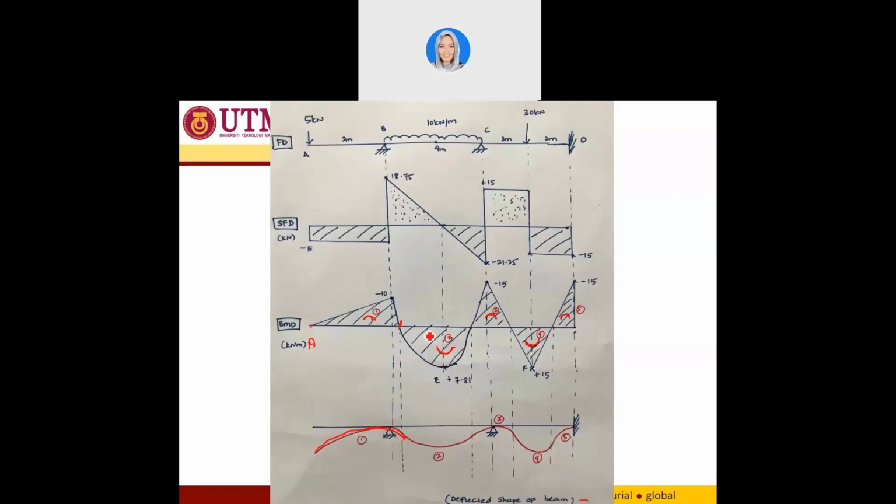Now between this point and this point, you have a concave down, a smiley face, so the deflection should be going like this. And from this one, you have a negative moment, so it is a sad face like this. So you have a deflected shape this way between this point and this point, and here you have again a deflected shape like this until this.